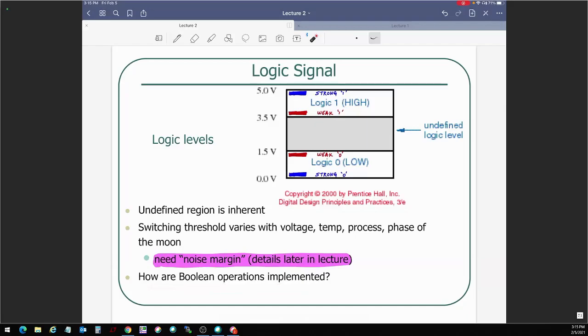We have to have an undefined logic level for all cases. Yes. So no matter what you're looking at, you will have that undefined region. The goal is not to be there, right? When you have hot and cold, you are going to say some temperatures are cold and some temperatures are hot, right? And in the middle, you would want some zone of temperatures that don't qualify as either hot or cold, because if you did, then the distinguishing factor between those temperatures, those levels, is going to disappear, right? So the whole point of having things in binary is lost if you didn't have that undefined region.